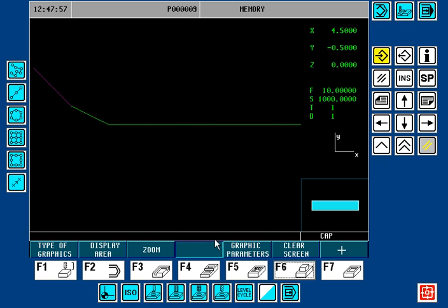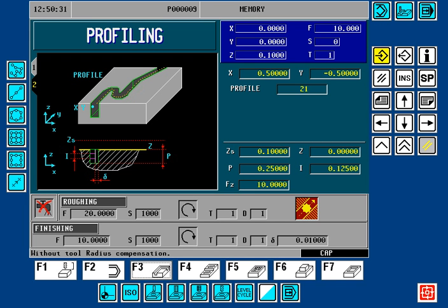And that's called collision detection. And that's a feature available in the G-code side. The conversational side is restricted to 1 and 2 block look ahead. With G-code collision detection, you can specify in your program up to 50 blocks in advance to monitor in your toolpath.